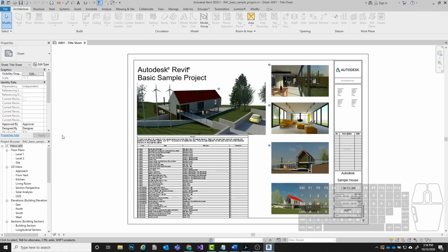All right. Now, if we're thinking about this in AutoCAD terms, right now we would technically be in paper space. Back in AutoCAD, we had those tabs, and we clicked on them to switch from the model space where we actually are doing our drawing. It's that vast infinite space where we're drawing our floor plans, and we transition over to paper space when we want to add our drawings to an actual sheet of paper and set up a sheet of drawings. This right here, the project browser, is what replaces that.